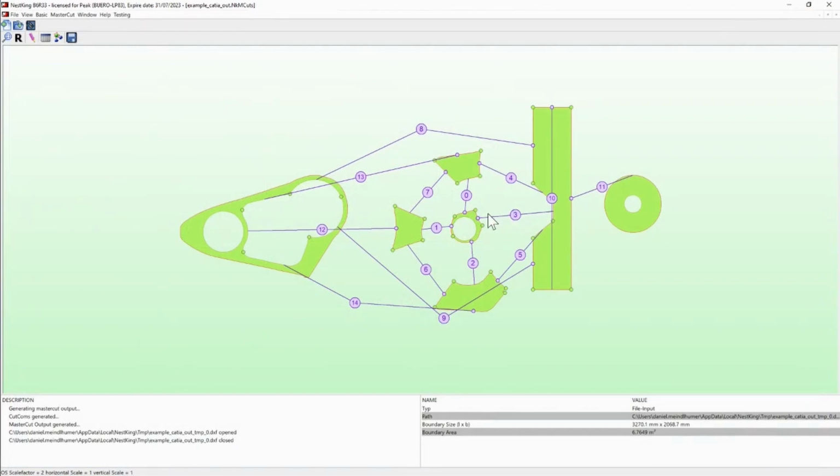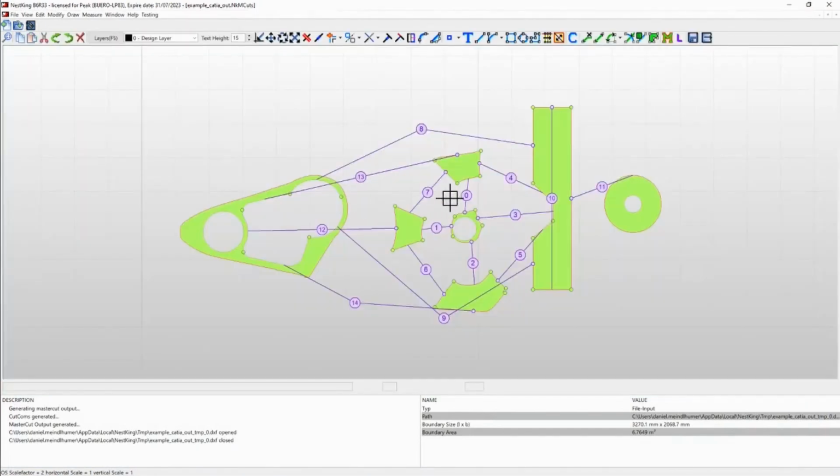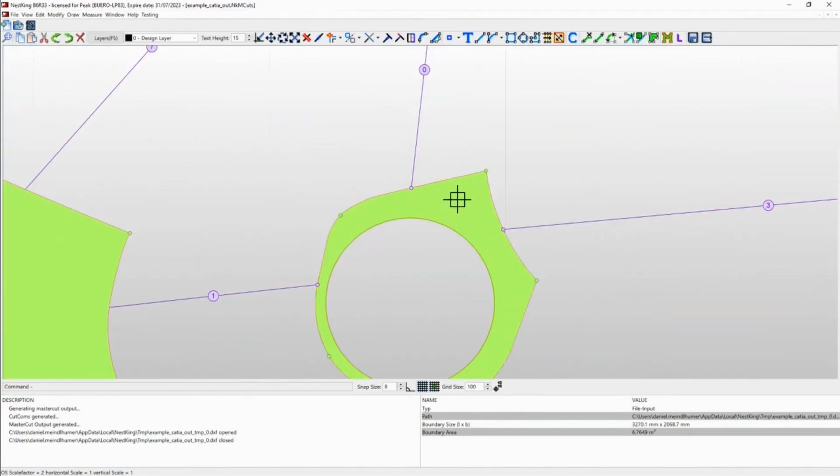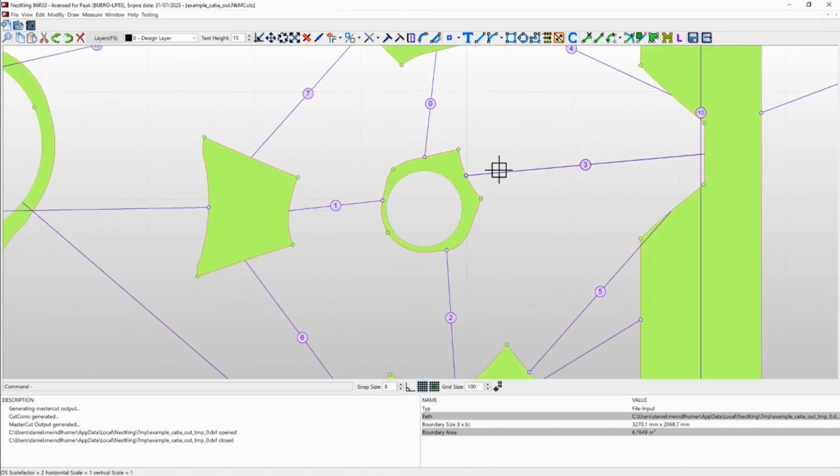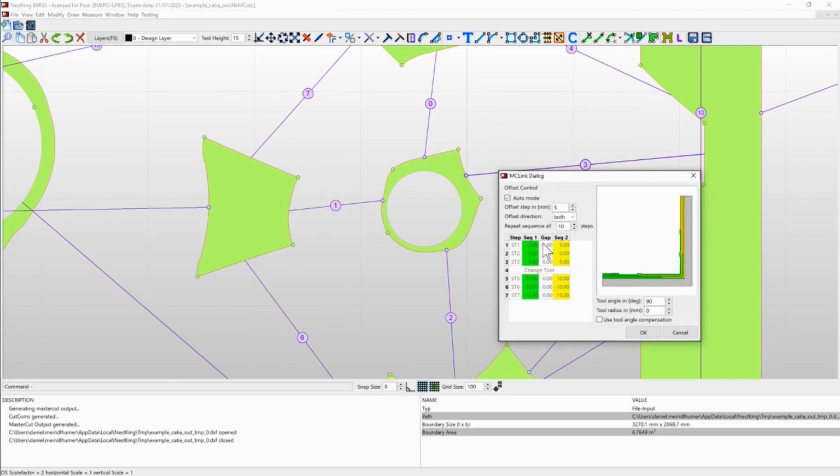To avoid this, we can, for example, go back into the sketcher area. Double click is not what we want to do. We simply want to set the direction, just in direction of the second segment. This is the second segment, and the segment with the point here is the first segment.